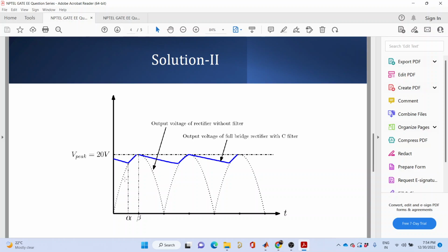Okay. So, a very rough way of saying it, it is just charging up to this value, and then it will stay put at this value, at the peak value. Correct? So when the load resistance is very high, or at lightly loaded condition, the average value across the capacitor would be very close to the peak value. So that is my worst case condition.